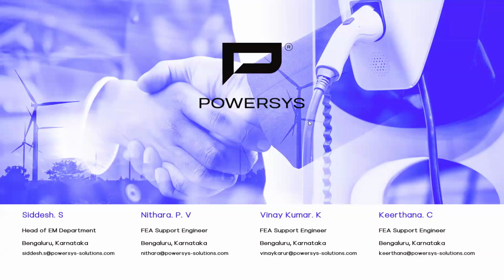Is this efficiency mapping the same for radial PM machines? Yeah, it is the same. How do you generate Ld Lq maps? Once the efficiency map is created, you can view all the results for Ld Lq and Id Iq there. We have options for that. What was the rotor structure of the axial flux motor used in your presentation? It is a frame and magnets embedded in it, right? Yeah.